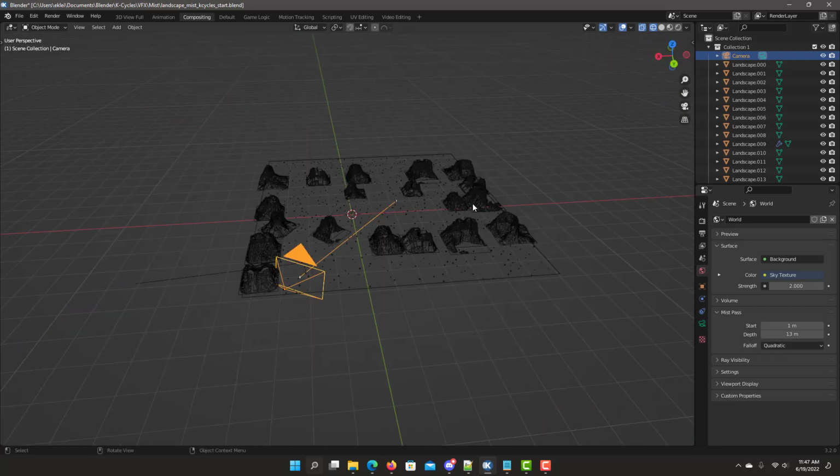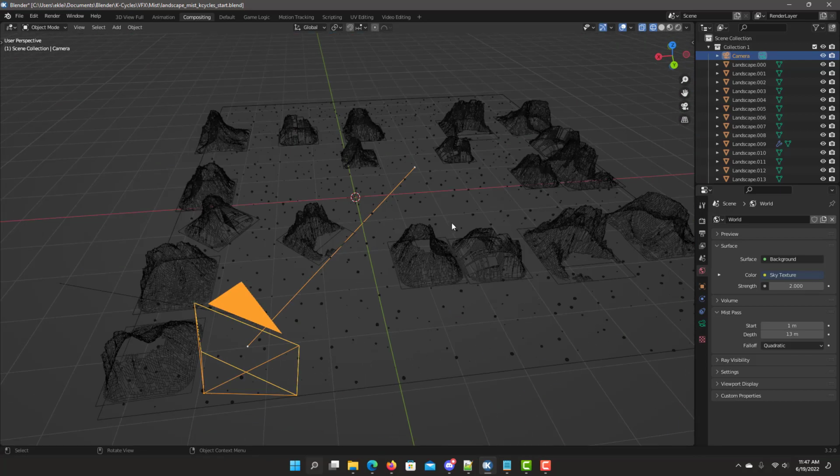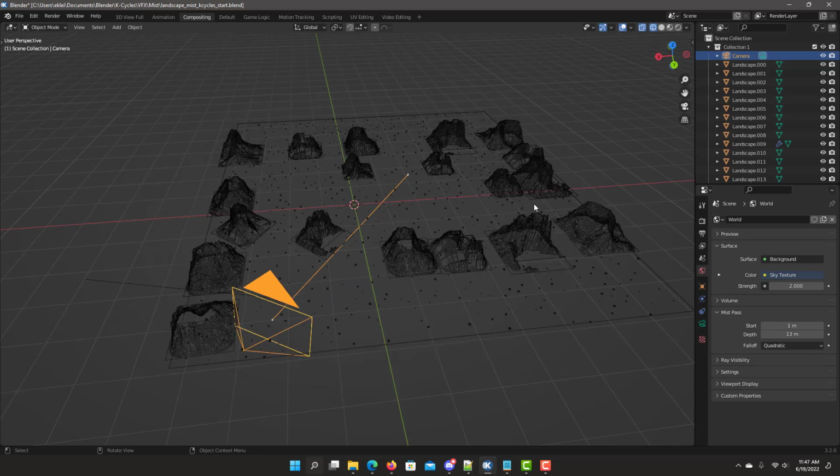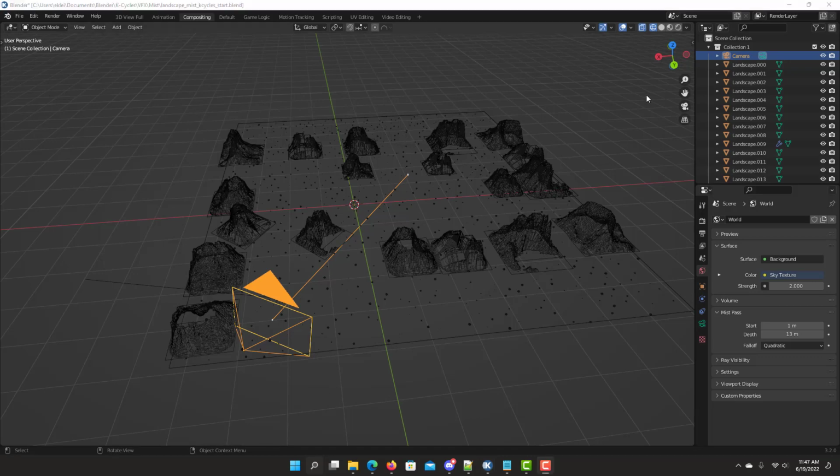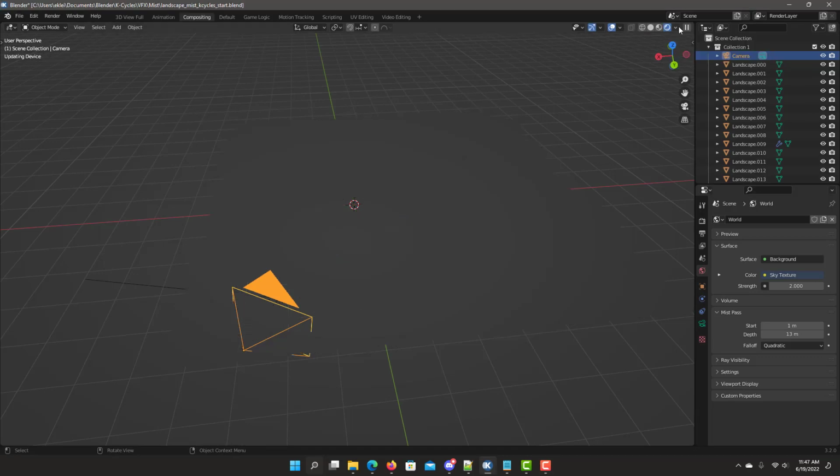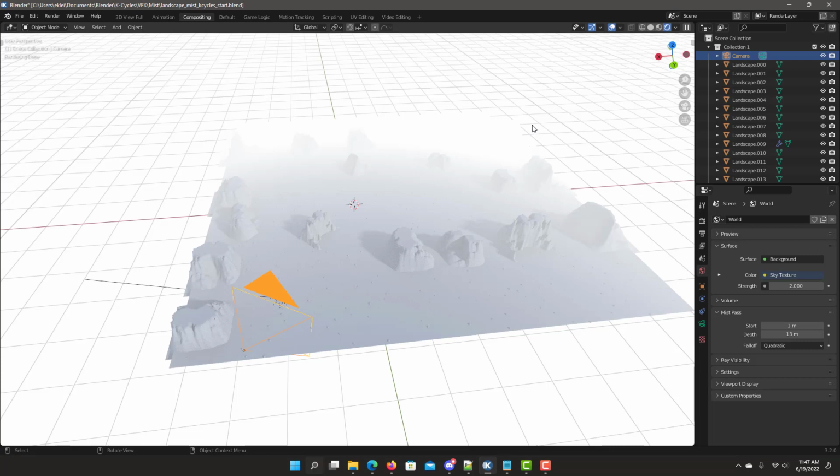Get out of this mode, into 3D perspective mode, where you can actually view the scene at a similar angle to the camera to look at how some of the settings of the mist change. Enable preview render mode, and you notice that you already have some mist in your scene. Try to do some adjustments to it.